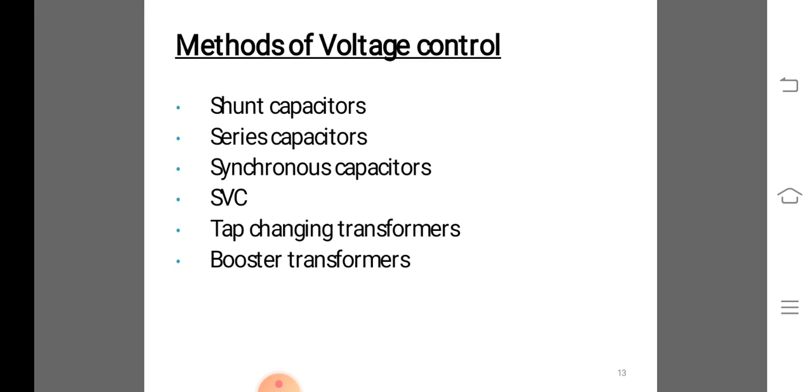Shunt capacitors are used for reactive compensation. Simplicity and low cost are the chief considerations for using shunt capacitors. Further, for an expanding system, additions can be made easily. The connection of the shunt capacitor through the tertiary of a transformer is the most important connection in shunt capacitors.